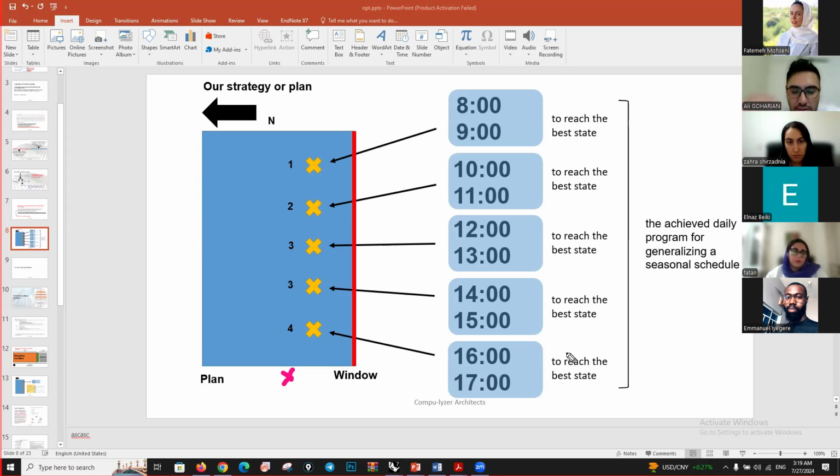As you can see, some simulation workflows are grid based. For example, for estimating and evaluating energy performance, it is not grid based. It's zonal: you achieve output, but zonally, not locally, and it's important. But for daylight simulation, we produce a grid as test points or sensors, and also for thermal comfort, you have to produce the grid base, test points, or sensors.